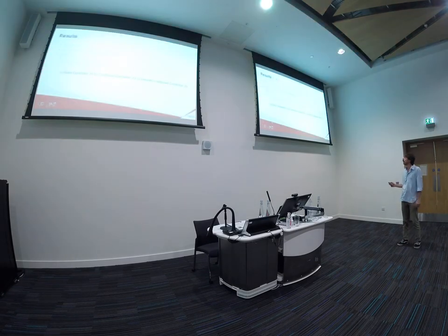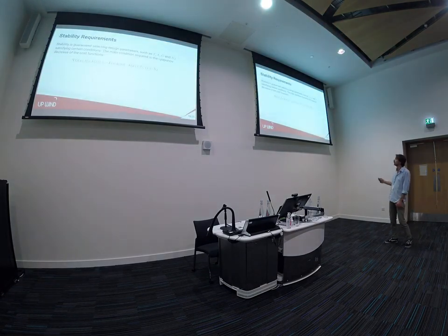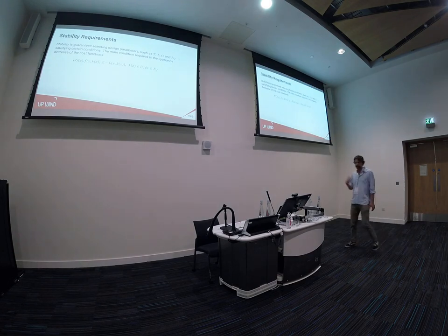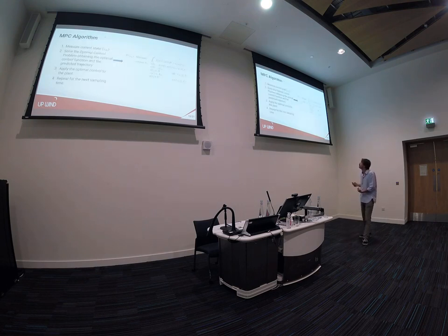Yeah, sure. Usually in this type of MPC architecture, when we say we want to prove stability, we're saying that at each time step we need to prove that the full cost function, the stage cost and the terminal cost, decreases. So it eventually will go to... You are going to consider that cost function as a Lyapunov function, for example? Yeah, we're going to use the Lyapunov function.